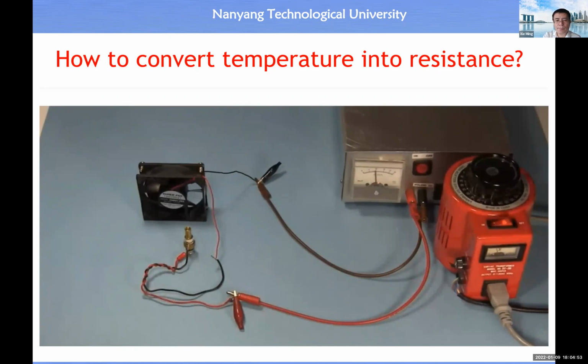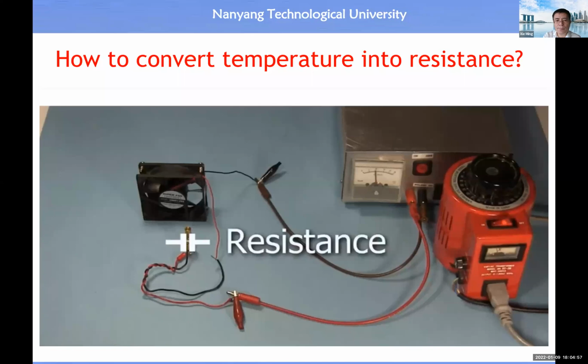That's because the thermistor is nice and cool at room temperature, and so it has a high resistance. The fan needs a certain amount of electrical current going through it in order to spin. But the higher the resistance in the thermistor, the lower the current is going through the fan. And the resistance of the thermistor is high enough to make that current too low.